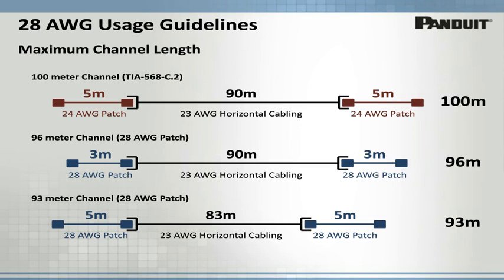Great. So the question, if I understand it correctly, has to do with basically, as I show in these examples, both the patch cords on both ends are of the same gauge. The question, as I understand it, is what if one is a 24 gauge, such as at the workstation, and the other is at the 28 gauge? Well, then you actually have a situation, the same derating formula applies, but now because you have patch cords of different deratings, you've got to have two different patch terms.